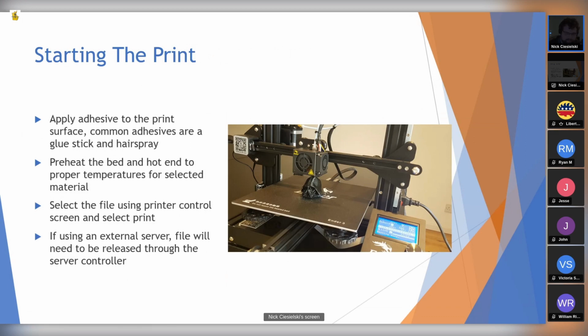So I have a piece of glass sitting on top of the metal heated bed and held with 4 clips, and I'll spray that piece of glass with hairspray before each print, and I've never had an issue with it pulling up. Oftentimes you have to wait for it to cool down enough to pull away and start shrinking just a tiny bit so that you can get the part off, especially if it's a thinner part.